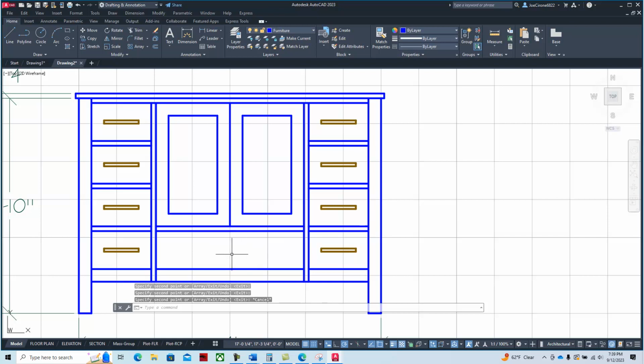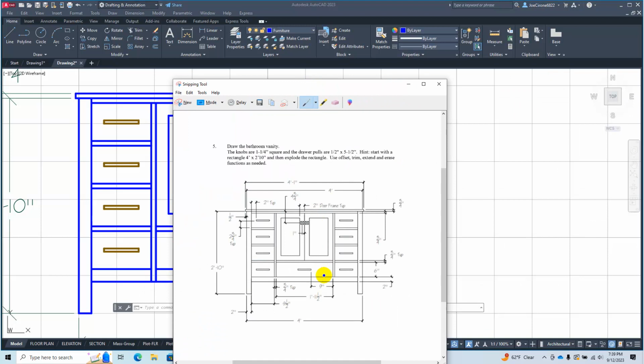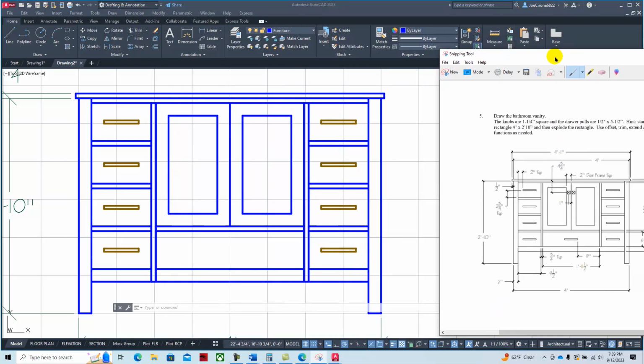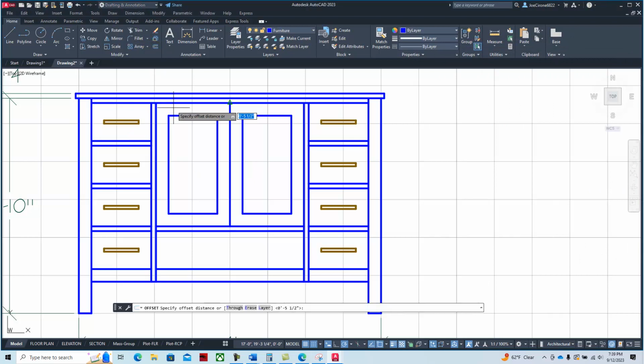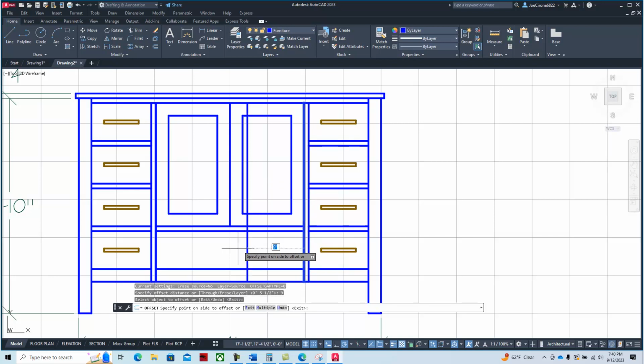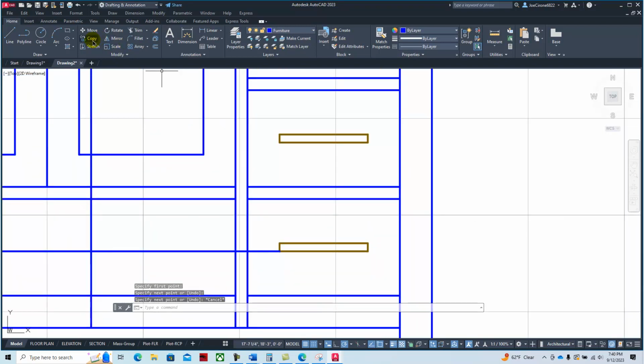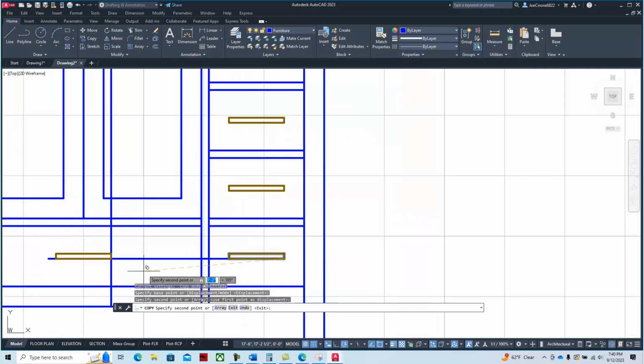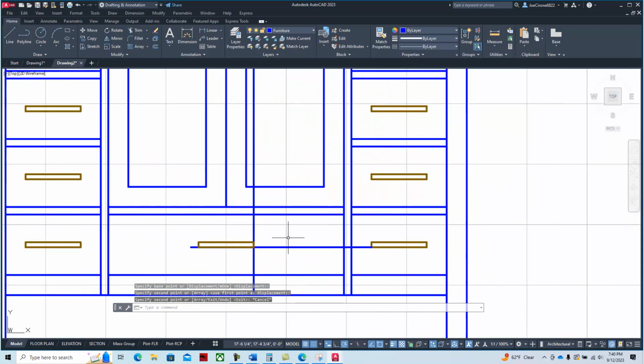All right. We need one more here in the middle, and this one is located 9 inches from this edge. Again, we'll just use the offset command, and then we can erase the line afterwards. And then what we'll do is copy this one straight across here. A lot of times I'll make a construction line so I can see where that lines up. And then I'll copy it using a blue window, which only selects the brown geometry, and I'll copy it from this endpoint to this endpoint, or to that intersection. And then erase the construction lines.